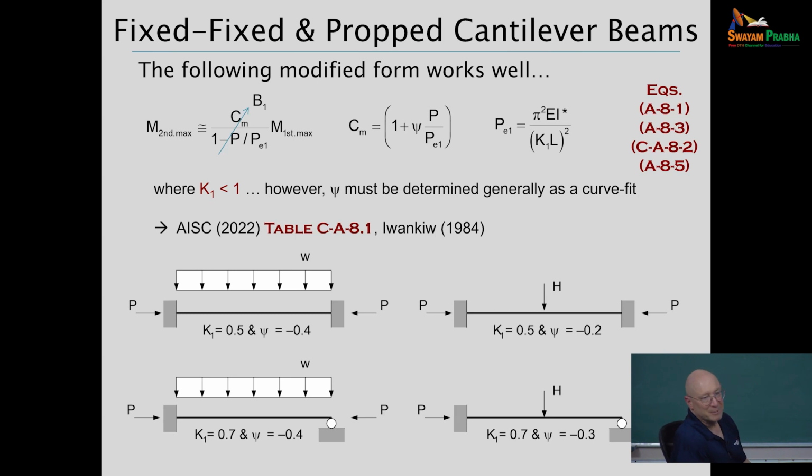Now you might have noticed that I've got a star next to EI. That's because in the AISC specification we have something called the direct analysis method, where we start playing games with reducing the stiffness to get a better calculation of what we think the moments are in the physical structure. I'll say a little more about that as we move along, but it's really only the Americans that are doing that. The Eurocode is based more on an Ayrton-Perry approximation. We'll talk about what that is and how that works.